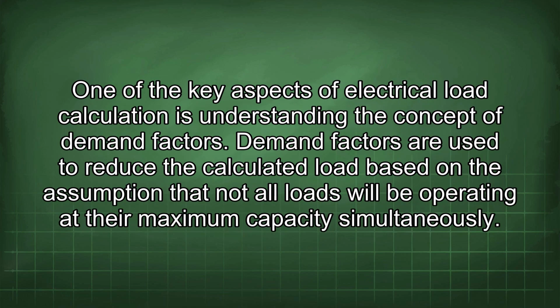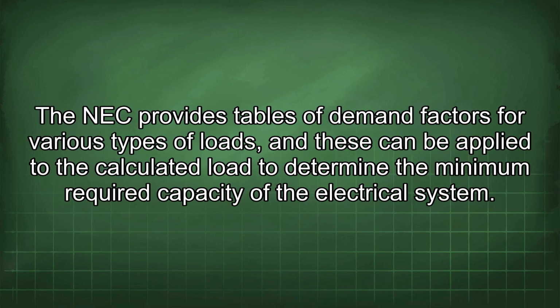One of the key aspects of electrical load calculation is understanding the concept of demand factors. Demand factors are used to reduce the calculated load based on the assumption that not all loads will be operating at their maximum capacity simultaneously. The NEC provides tables of demand factors for various types of loads, and these can be applied to the calculated load to determine the minimum required capacity of the electrical system.